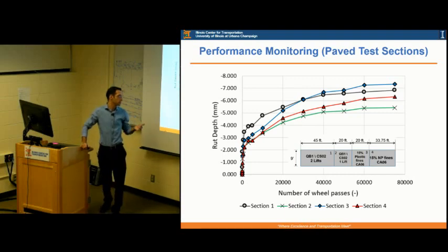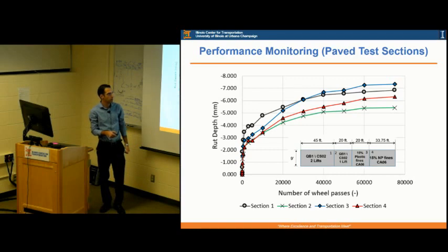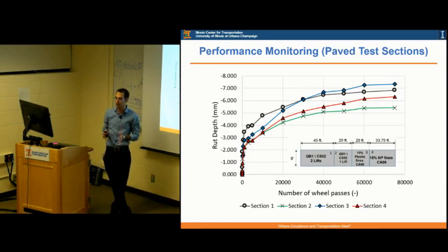Section 4 is 15% non-plastic fines. In this section, it's a regular base course material, but the specs in Illinois now permit you to put up to 12% fines only, and that's the maximum amount of fines that you can have in your CS6 material. We're trying to get 15% fines instead of 12% fines. If you get higher fines and can show that it performs well, then eventually you end up producing less quarry byproducts in the future, because you can permit higher fines in the material that you ship to construct roads with.